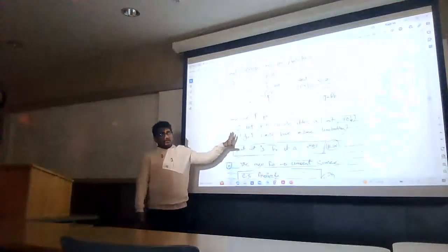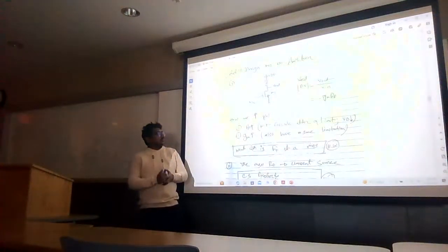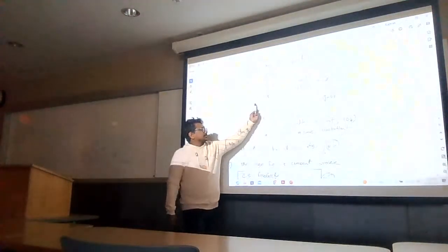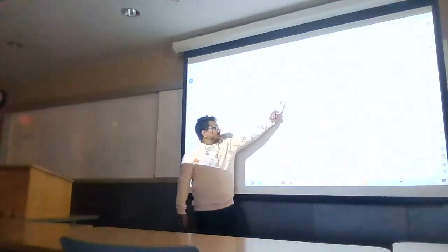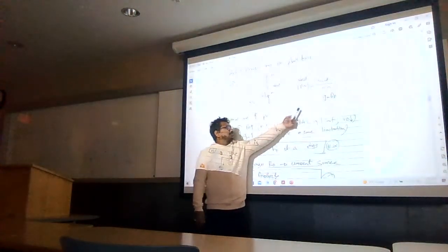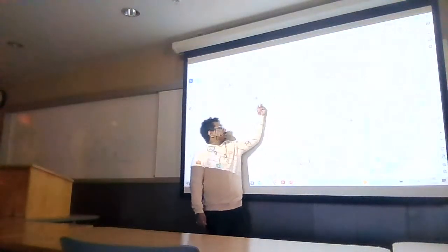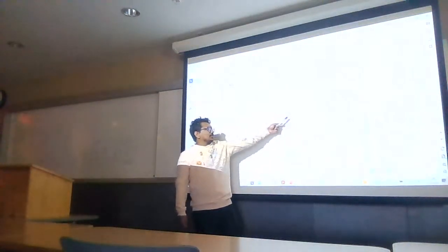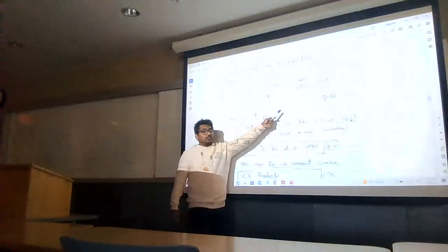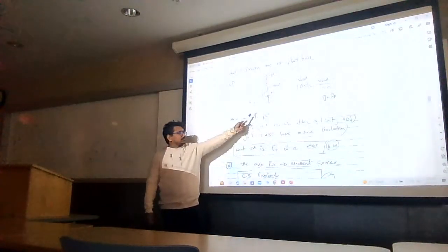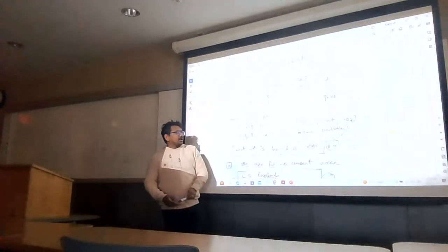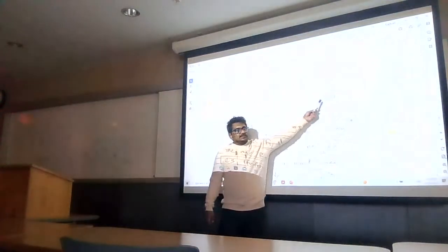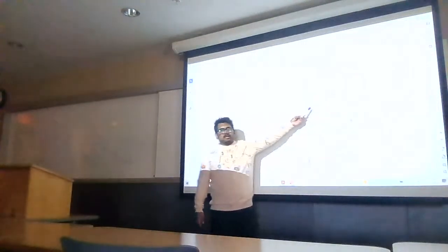Here I'm not discussing the small signal model itself, but from it we calculate the output by input ratio. This is the gain of the amplifier, and the gain is minus GM times RD. How does it come? It comes from small signal analysis. So if I ask you how I can increase the gain of the amplifier, how can I increase the gain?